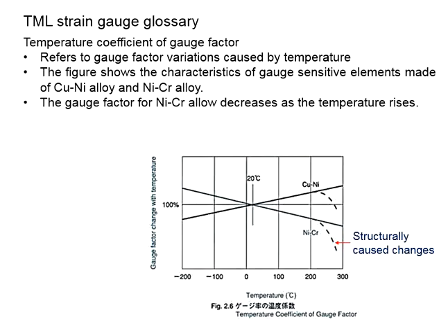Temperature can lead to expansions of the sensitive element in the strain gauge, and the expansions of this sensitive element shall change the cross-sectional area of the element and influence the resistance of the strain gauge. Now the strain gauge resistance changes. By computations, there will be strain even though it does not exist.